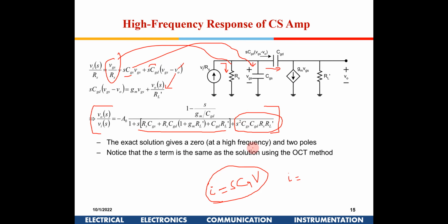Yeah, tell me. So in this, why have we taken it as a current source, as CMOS is a voltage controlled source? This is gm VGS, right? Yes, sir. So it is a current source only. Input side we are voltage controlled, right? Yes. So gm into VGS.